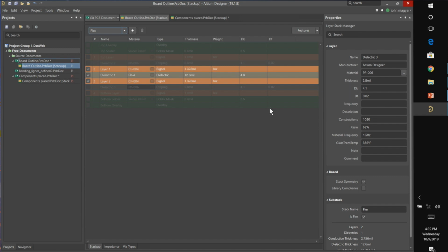And then you can tie a cavity into that, so small terminating resistors, things like that can be embedded directly into the flex, and then you can control the thickness in the layer stack up of the flex. So certainly all possible there. But yeah, the stiffener, that's one that's been on the list for quite a while.